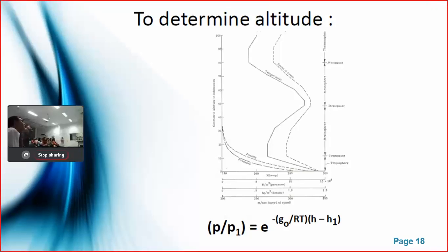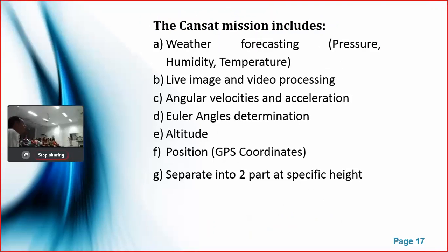We have many sensors in the CANSAT with a great time requesting function, so the value of the angle is not accurate enough. So we are forced to use the ADXL345, which is not so accurate in determining the value of the angular acceleration, as there is no gyroscope in the design of the sensor. After that, we talk about the altitude.